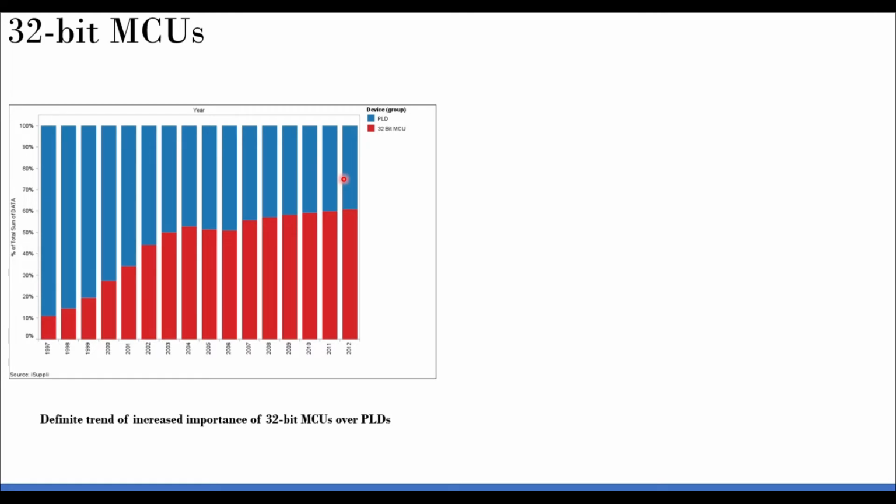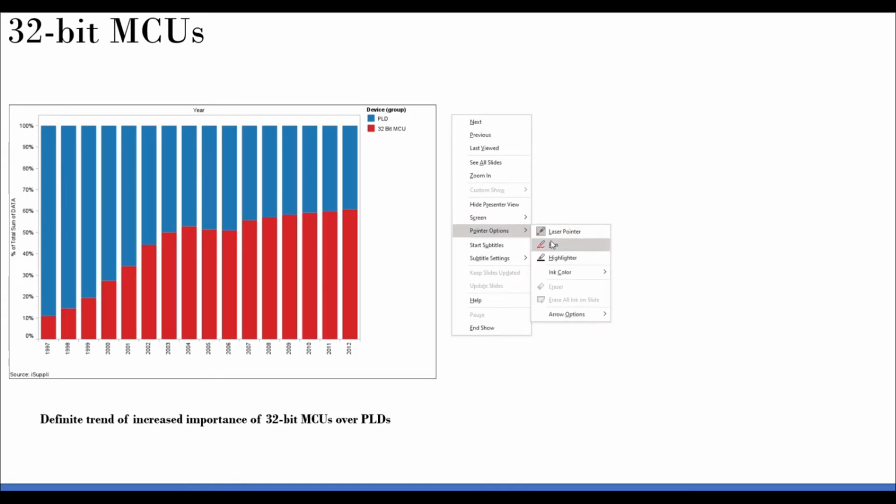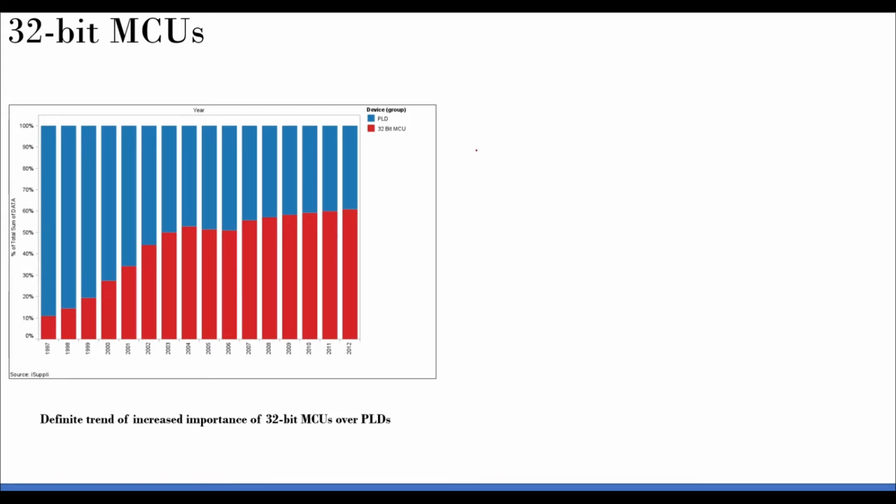Maybe you have not studied that, so let me quickly brief you on why the accuracy is better. It's a slight digression, but it's very important to know. So why is 32-bit more accurate than 8-bit? Let's say I have a waveform, some analog waveform. When I say it is 8-bit, this is analog, so I need to convert it to digital. There is of course discretization in time and discretization in amplitude. And when we talk about bits, it's all about discretization in the amplitude.